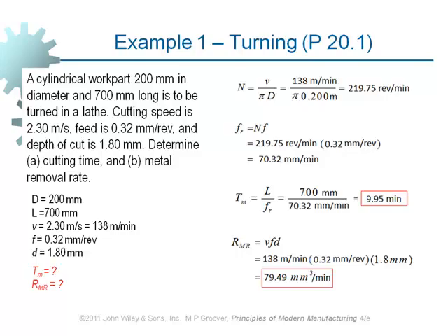How does it work? In the textbook, in the handbook, you are not given a specific cutting speed for an operation. You are provided with a range. From this up to this. This is minimum, this is maximum that you can use for the cutting speed. So if you play with spindle speed, you can still stay within the range. Slightly higher or lower wouldn't make a big difference. Okay? So keep this in mind.